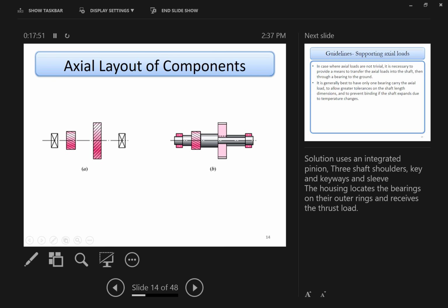As you can see, one of the solutions here is to come up with a stepped shoulder layout to carry the two gears and also locate them using the shoulder. The same thing goes for the bearings here. Between this gear and the bearing, there's also a sleeve, basically to prevent it from moving away axially. And then the small gear here, which is possibly a pinion.